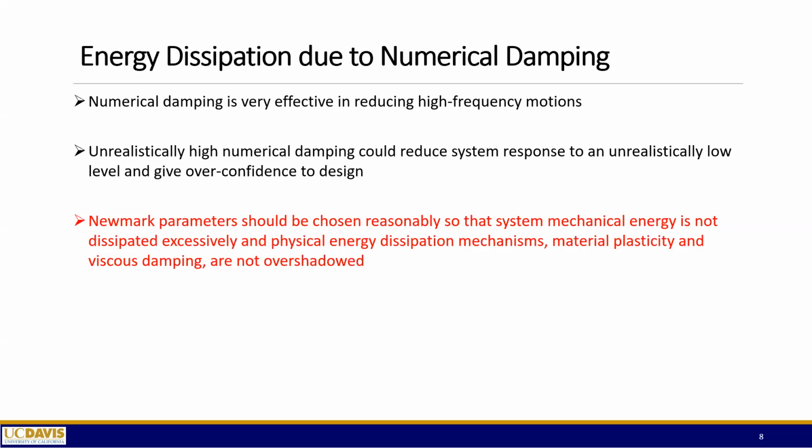One has to be careful with that, because remember, the viscous part is velocity proportional, and the plasticity part, the material part, is displacement proportional. So for different velocities and different displacements, you get totally different results. So you're right, you can maybe fit one point, PGA or one of those, but you cannot replicate the actual response of the system. Go ahead, please. Yes, exactly.